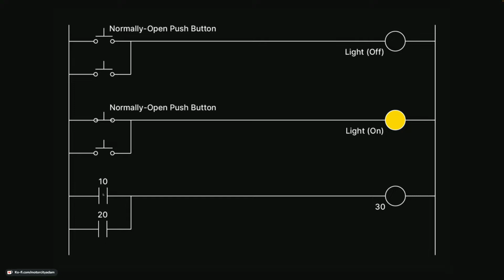Okay, so while these blocks are false, meaning that the button up here is not pushed, this light will remain off. You can see that these buttons are connected in parallel here. Once either one of these push buttons is depressed, either one of these blocks here will toggle to true. And that will mean that this whole rung evaluates to true, and then the light will turn on.